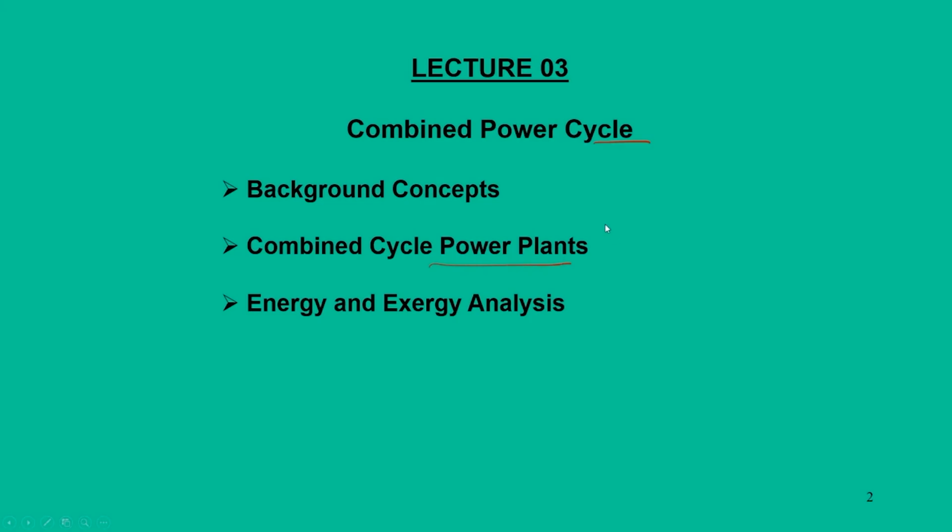Towards the end, we look at the combination of two different concepts, like the combination of steam with gas, and the combination of nuclear power plants with gas turbine power plants. There has to be some basic minimum justification to work them in combined mode. For such cases, energy and exergy analysis is very vital. When we combine them, we are essentially increasing the infrastructure, capital cost and complexity of the systems, but that has to be justified with the need of technical requirement.